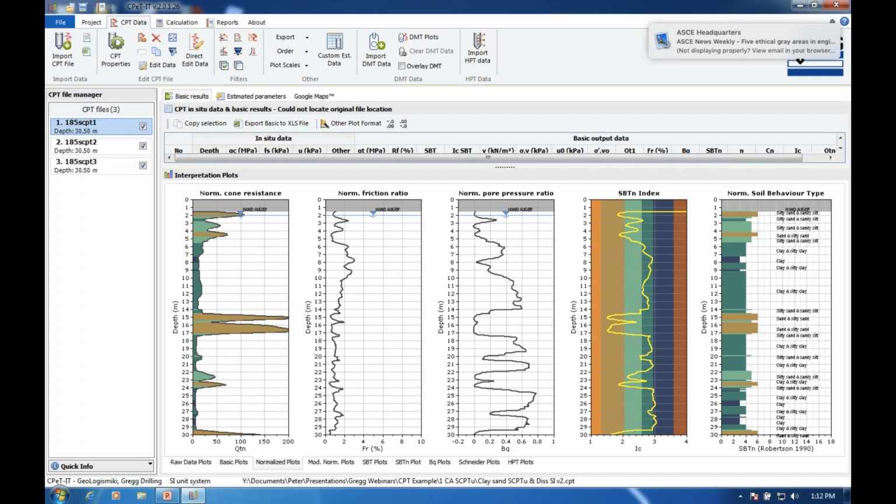And so if you've got unsaturated soil, this is quite a nice way to get a pore pressure profile in unsaturated soils, because you're trying to inject water into the soil and you measure the pressure required or that's created as you try to inject it in.